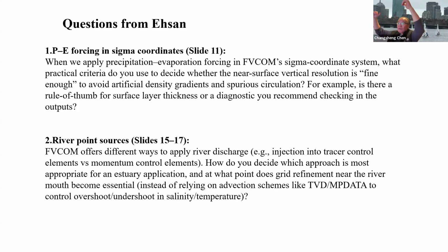So you put a uniform precipitation water into the first layer as the surface boundary condition, but this water will go to the whole layer, and if the first layer is not uniform, some regions can cause trouble. Precipitation directly affects the surface boundary condition for sea level,